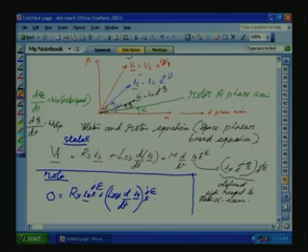Now, let us take the mutual inductance. Due to the current in the stator, there is a coupling, there will be a flux generated, that flux is proportional to that current and the mutual inductance which would be coupling to the rotor. Now, this is M into d by dt IS. IS is originally defined with respect to the stator.